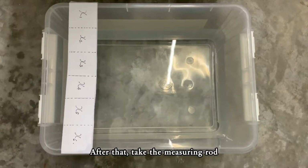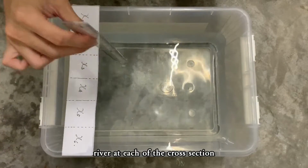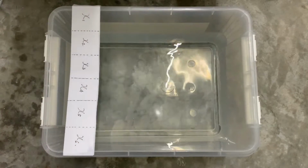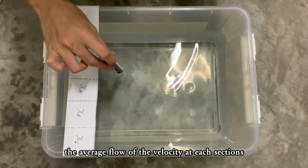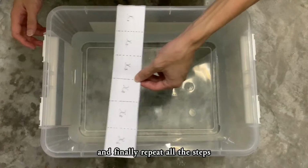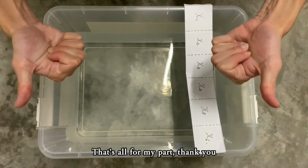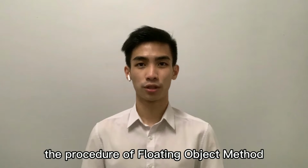After that, take the measuring rod to measure the depth of the stream at each of the cross-sections. After that, the current meter is used to record the average flow velocity at each section. And finally, repeat all the steps for the second stream cross-section. That's all for my part. Thank you.